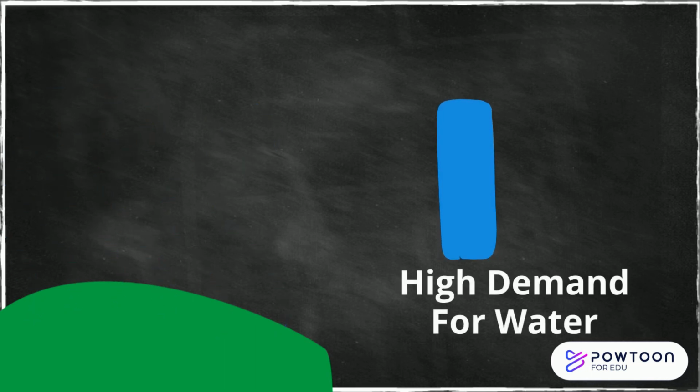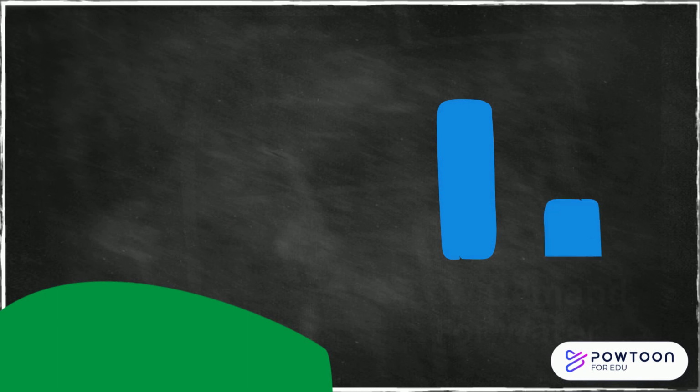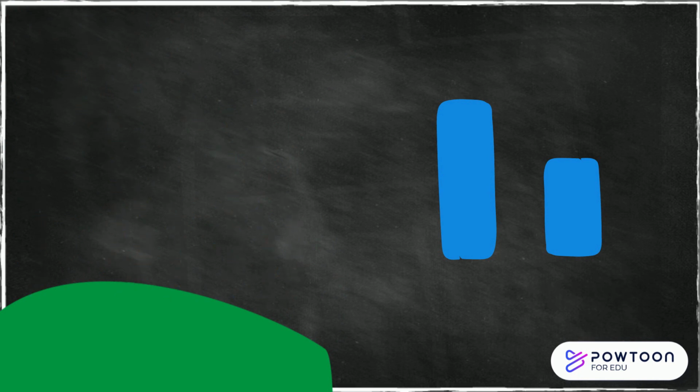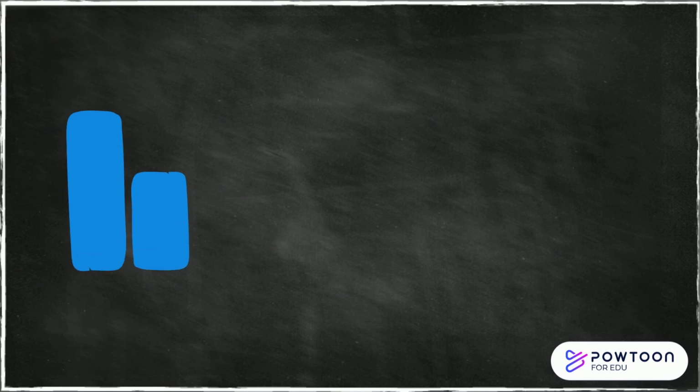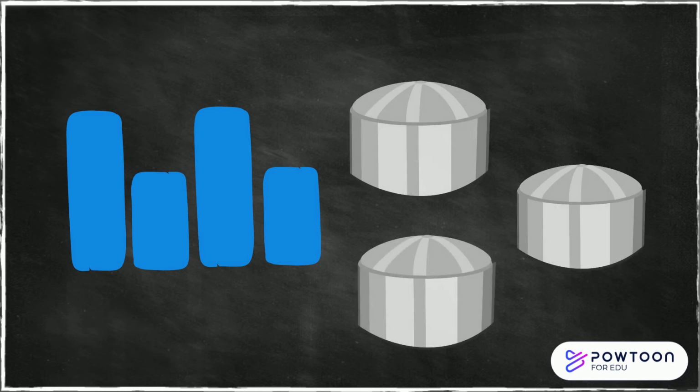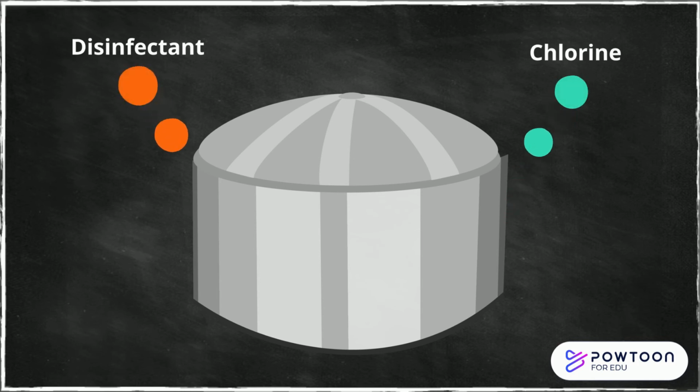During the summertime, when people water their lawns, there's a high demand for water. Some days when it's raining a lot, there's a low demand for water. If you are constantly meeting demand and not having a surplus, then you are pumping more and pumping less and pumping more and pumping less. So the clear wells help soften that, right? You use your clear wells to provide during high demand. Clear wells are also used to provide chlorine or disinfectant contact time.